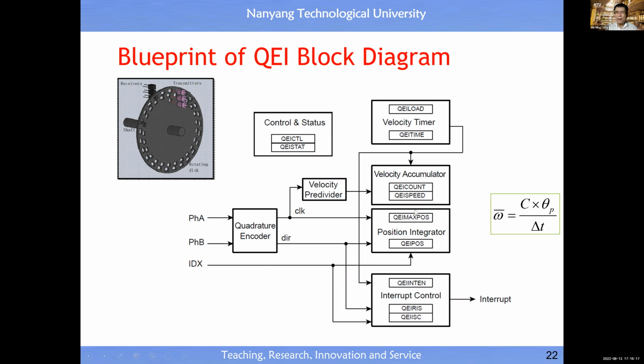And the implementation here is actually very simple, because for the velocity sensor, you remember lecture 1, we just have a counter to count the number of pulses. Each pulse corresponds to a displacement. This displacement could be angular displacement or linear displacement, all right? Then we define a time window or a measurement period. So we use this term, a measurement period, all right? So this value is this value, low, okay, use this term.